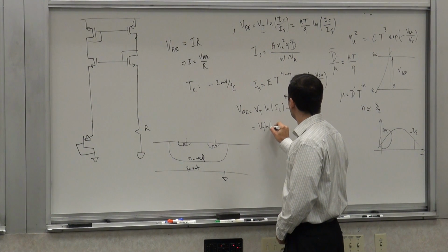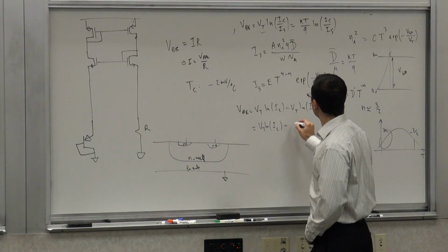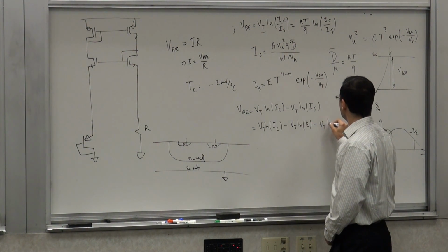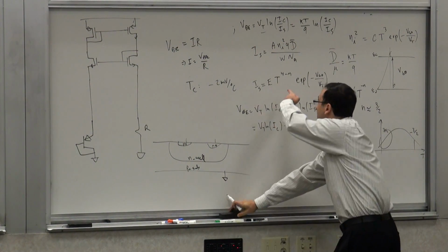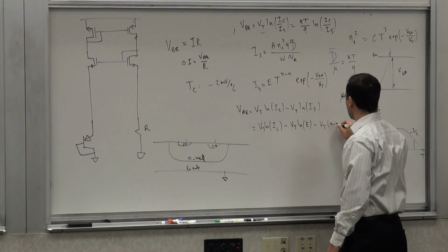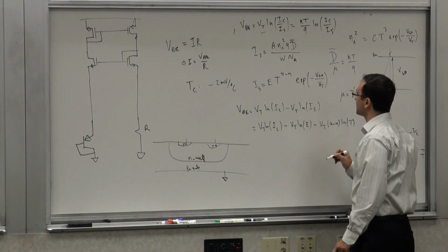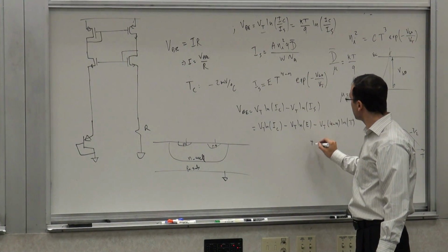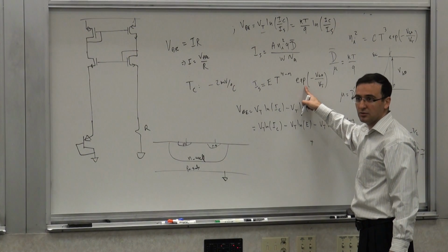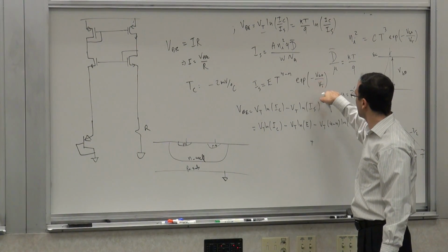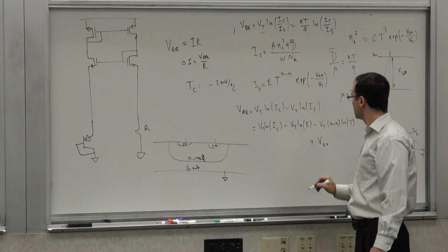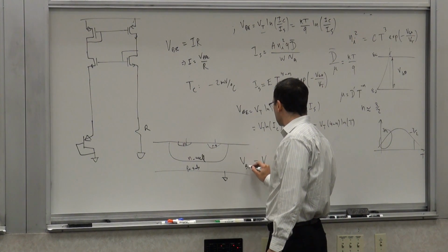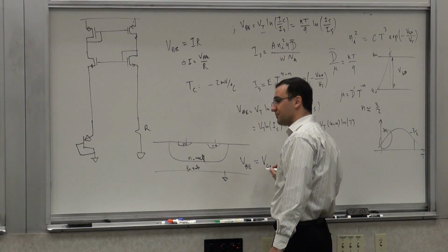So VT ln of IC minus VT ln of E minus VT ln of T to the 4 minus n, and the exponent comes out, so we get VT times 4 minus n ln of T. And there's a minus sign here, so it becomes plus, so it's ln of an exponential. You get the argument, the minus sign cancels, a VT cancels, so it's plus VG0.